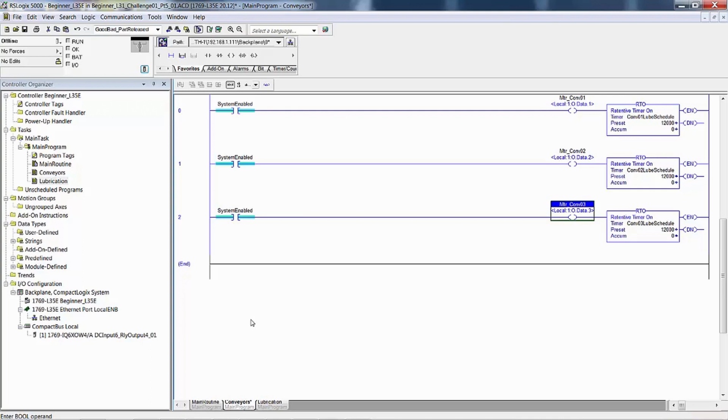They come to the entrance of conveyor 1. Conveyor runs until the carton's all the way on, then stops. Next one shows up at the entrance. Conveyor turns on, and then there's 2 on there. Once the conveyor is full, the last carton is pulled on there, the next one that arrives should turn on conveyor 1 and conveyor 2. That way the new arrival gets pulled on to the entrance of conveyor 1. The first one that was on conveyor 1 is now the first one on conveyor 2, and so on. And then we would do the same thing with conveyor 3 when parts are called for.